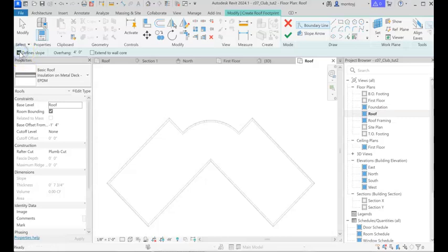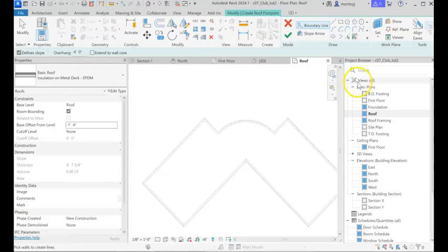We want to define a slope because we have a sloped roof for this first one right here. The overhang is going to be 4 feet. So with my slope condition, I'm going to come in and adjust that after I lay down this roof. Okay, we're going to do pick walls, so let's pick them. That first one didn't take, but we're just doing this particular wing first.